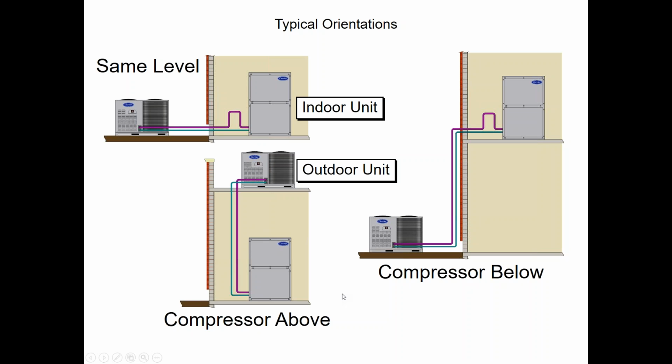Now, that was mainly refrigeration duty. I think Trane may have done that for some time in their DX splits. At Carrier, we've never done that. We've gone to either speed risers, which is a downsized suction line in the verticals, or we've gone to double suction risers, which I'll get into in more detail and show you the charts in a little bit. Currently, no traps at the top of a condensing unit. When I say condensing unit, I'm talking about a compressor bearing condensing unit. If I was talking about a condenser only with fans, that's another story which we'll catch up with today also.